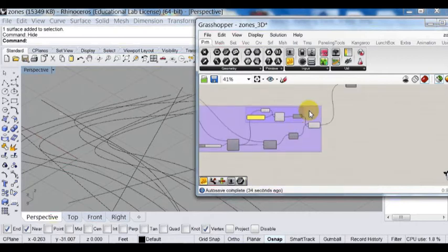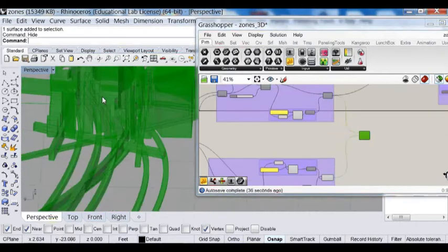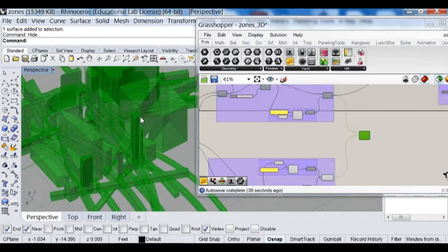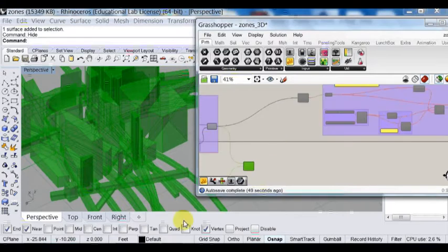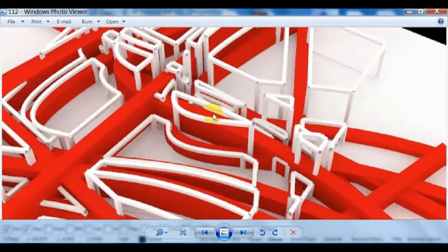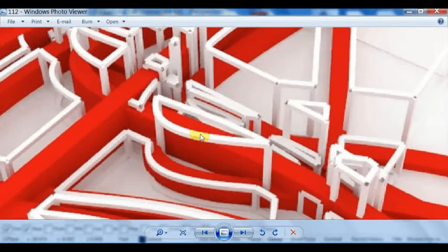So let's keep going. So we have the 3D models. Looks like a city, right? With highways, with building mass. The next thing I want to do is actually make it even more complex. I want to create some kind of frames. Look at this rendering, some frames. It's very similar to a super extrude, if you recall in Maya, right? You can take a polygon model, then when you do super extrude, every single edge becomes a frame.